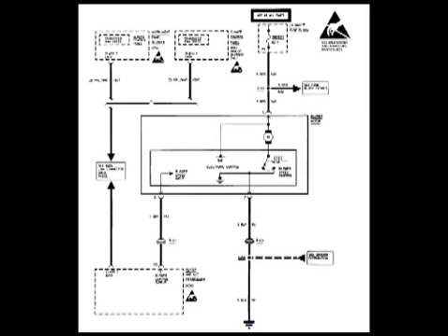As the speed request is lowered, the count should also be lowered down to around 30, which is full off. If the commands are as desired, the flowchart directs the user to measure the resistance of the circuits and the motor, then replace components as required. This method is not only time-consuming, but it also requires the use of the factory scan tool, which not everybody has. There are also faster and more direct methods to test this system.